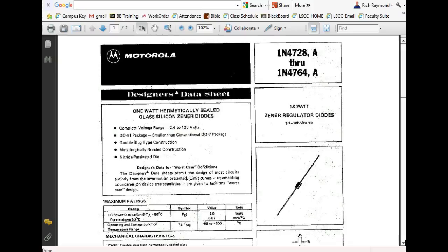How many of you got your Zener in there right? How many knew we was going to burn up the Zener? Yeah, and that's one of the first things you need to find out right off the bat. So now Zeners are rated in a lot of different things, but what's the two primary things Zeners are rated in? Watts and volts. That's their two primary ratings. Then they have a tolerance, right? And then they got IZK and IZT and all that other kind of stuff, right? But it still has a voltage, it has a wattage, and it has a tolerance. So you need to know all three of those when you buy it.